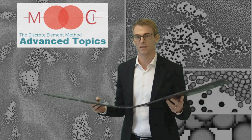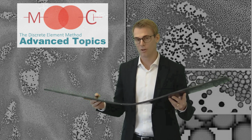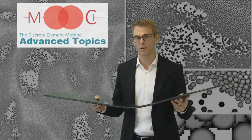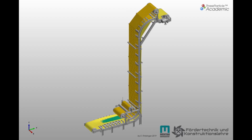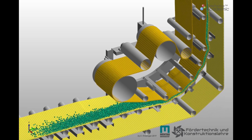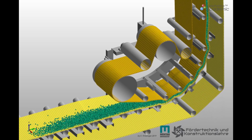So when instead set up as a bonded particle model, the belt is able to react dynamically and locally to loads from the bulk material on the belt, as well as to components keeping the belt in place, such as idlers and pulleys. An example of a belt conveyor system where this can be visualized is a sandwich conveyor, where the deformability of the belt is of significant importance. This system transports the material with it clamped between two belts. And of course, the capability to break can also be implemented into such a belt model's bondings.